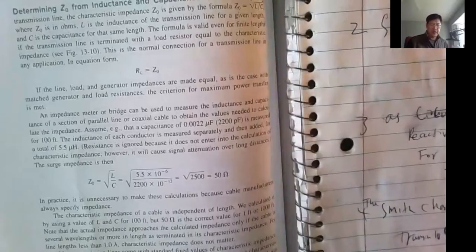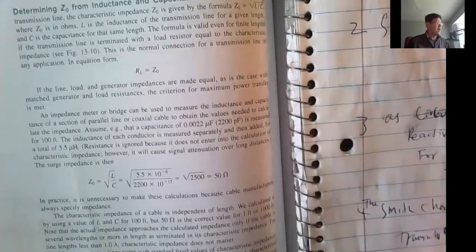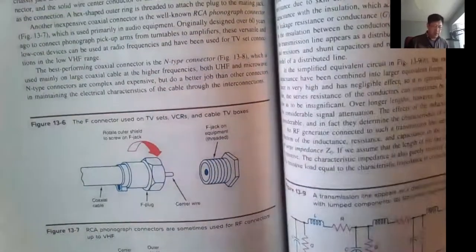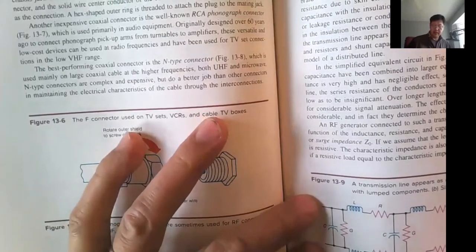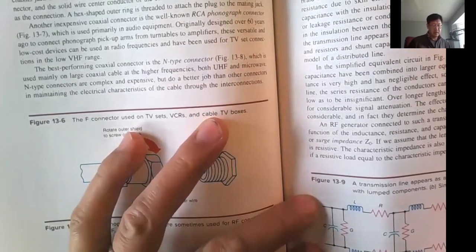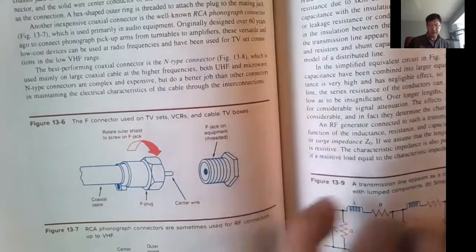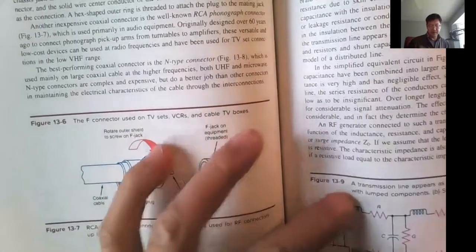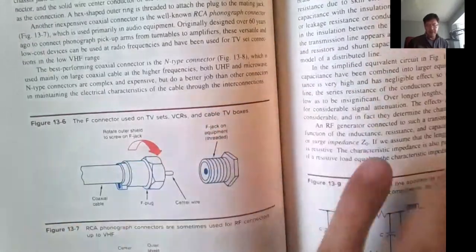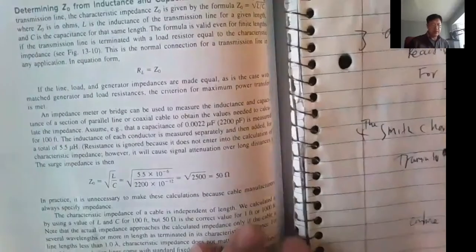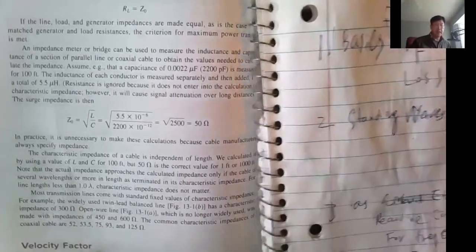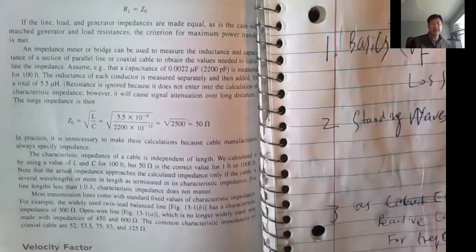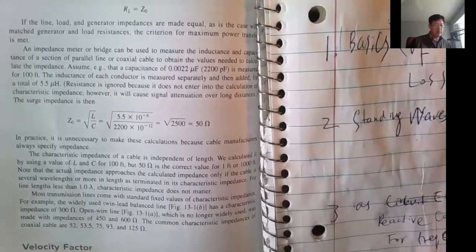So that's a characteristic impedance. When the power is connected from one side, the other side will not receive the signal unless all those inductors and capacitors are energized. So the signals will travel slower. That's the next topic, called the velocity factor. Because of those inductors and capacitors, it will really slow down the signal speed.